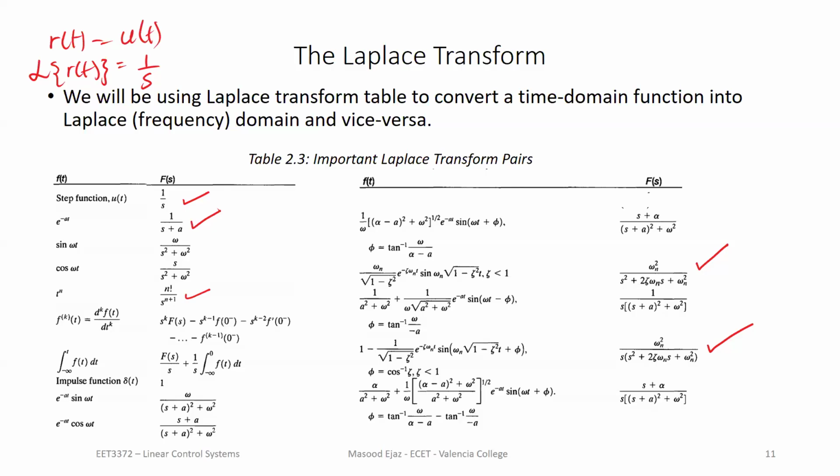So in order for this fraction to look like that, what do we need? We need in the numerator, of course, 500 exponent 6. That is omega n square. We already have 2.5 exponent 6. So if we do 2.5 exponent 6 divided by 500 exponent 6 times 500 exponent 6, we are not changing anything, divided by s square plus 500 exponent 6, which is omega n square. All right, now we can easily calculate the value of omega n, which is the square root of 500 exponent 6.